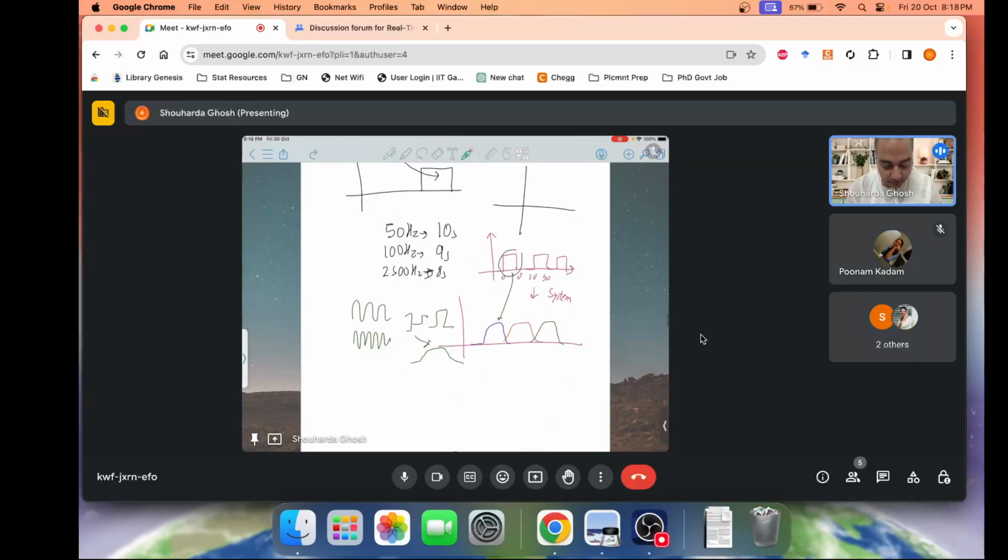But if you do not have a linear phase system, different frequencies will undergo different shifts in time, and the resulting waveform will be scattered in time. As a result you may encounter something called intersymbol interference, which you might have studied or will be studying in a digital communications course.